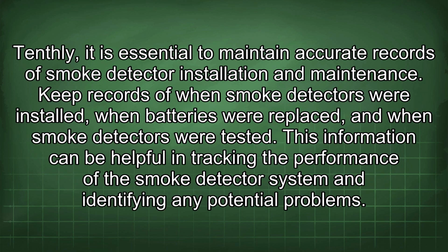Tenthly, it is essential to maintain accurate records of smoke detector installation and maintenance. Keep records of when smoke detectors were installed, when batteries were replaced, and when smoke detectors were tested. This information can be helpful in tracking the performance of the smoke detector system and identifying any potential problems.